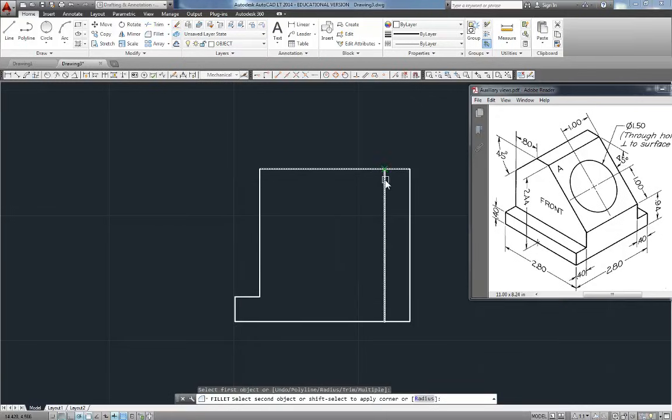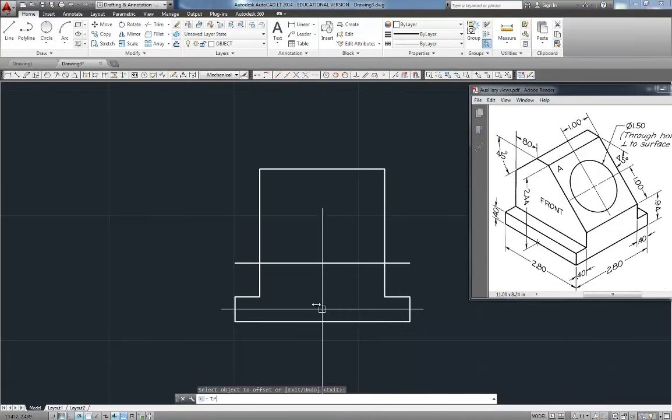And so it goes. I'm going to have to reconnect a line over here. The fillet command trimmed it away. And now I'll fillet it again. Fillet is a real powerful tool if you make use of it. I need this corner up here. It's up 0.94 as we can see. So we'll offset, O for offset, 0.94. And we'll trim that off.